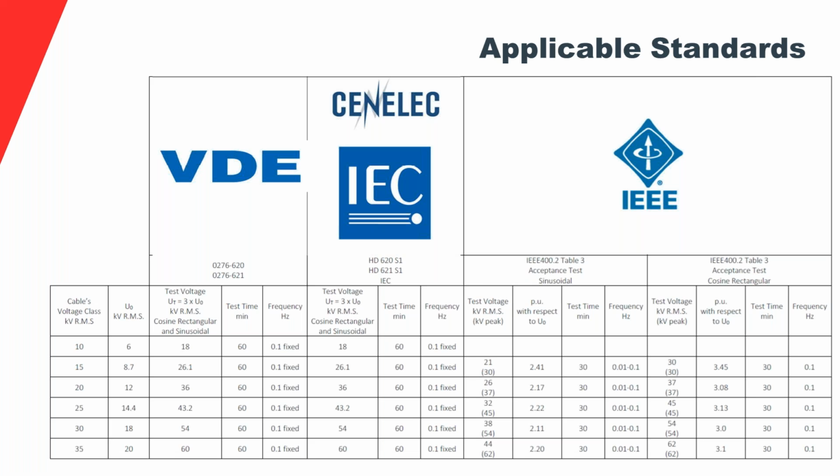Especially with the sinusoidal units, there's a maximum test capacity based on the total length of cable and the capacitance of the cable. There's a maximum test capacity that the sinusoidal test unit can energize at one point. So if you parallel 3 cables, you put 3 times the length of cable on that VLF test unit, and it may exceed what that sinusoidal unit can test.